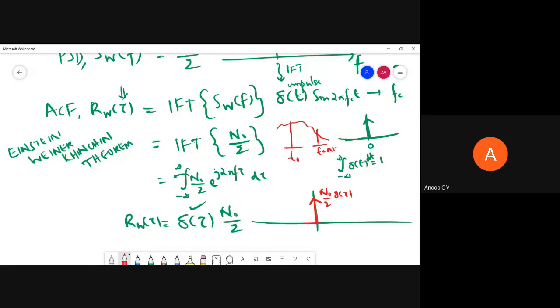So here, what it says is a signal will have similarity with a delayed version of itself if and only if the delay is equal to what? 0, which means a signal with itself, without any delay. If you take a sample, it has correlation with only that particular sample. Any other sample you take at a different time instance will not have any correlation. It means it's completely random. You can't find any sort of periodicity, any replicating part or periodic nature. It won't repeat. So that is what is given by this autocorrelation.